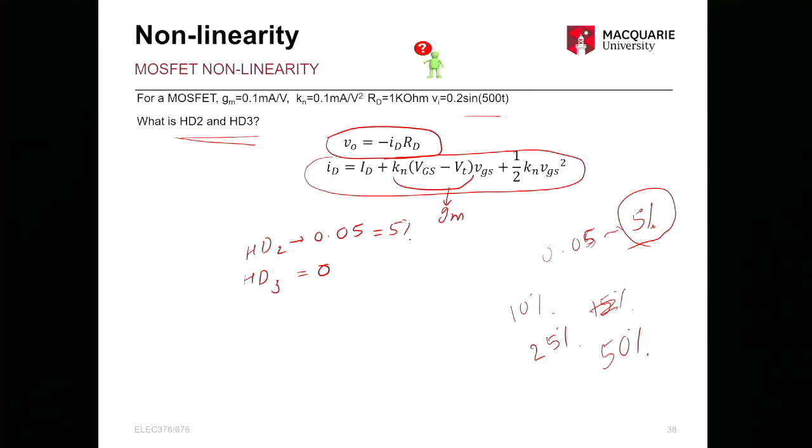Then you have the gain, so you multiply them together. Or you may have to change the gain to dB. When you have the voltage gain, you find 20 log of the voltage gain, which will give you the voltage gain in dB, and then you multiply with the bandwidth.